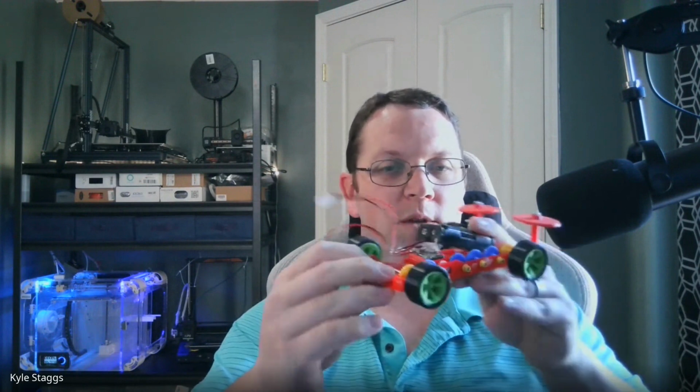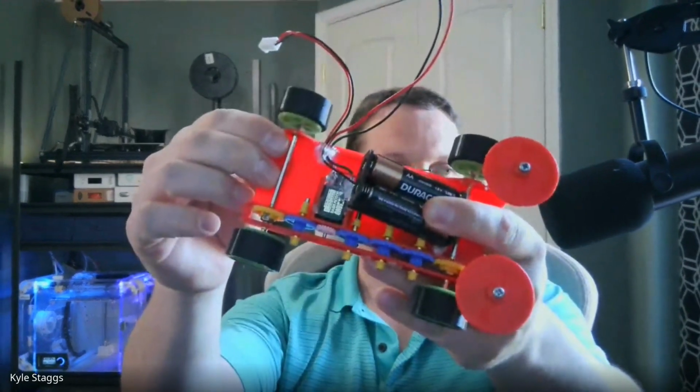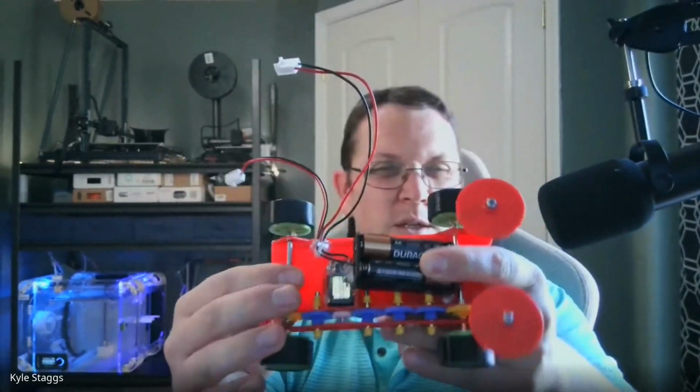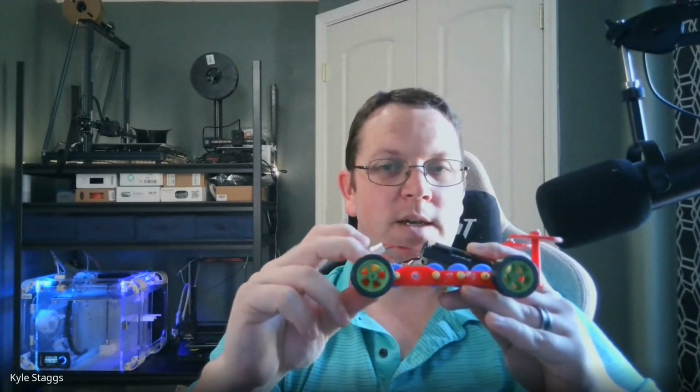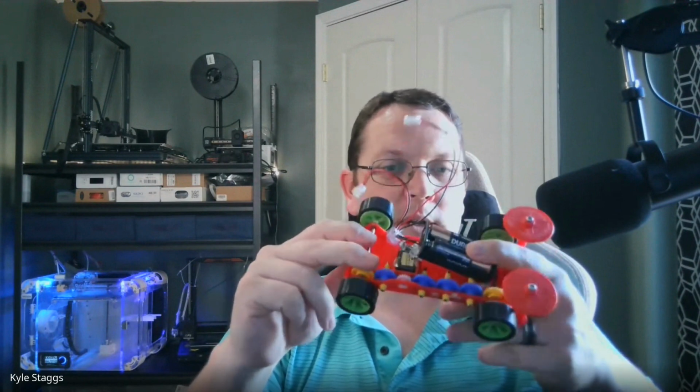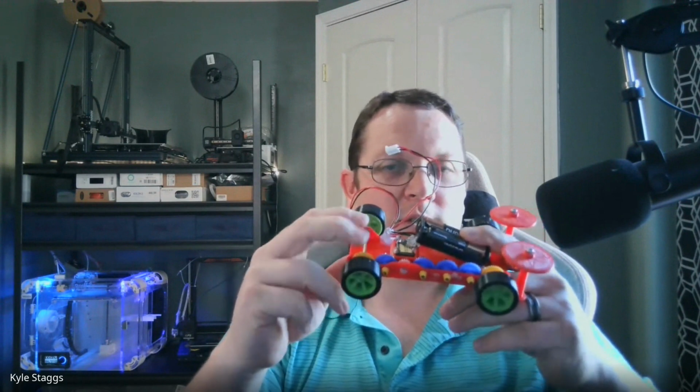The rollers don't have to be mounted to the rear. They can kind of help keep the car straight so that it's not just trying to track down the track sideways or something if your axles are hugely misaligned. So it can help. My experience has been the difference the rear rollers make compared to the front ones is almost nothing. So it'll help kind of keep the car square in the track. But honestly, I've not found them to be necessary for this particular assignment. You can get a car around just as fast with front rollers only.